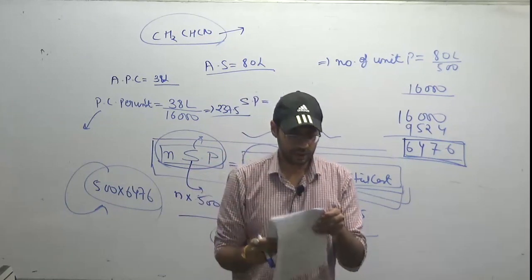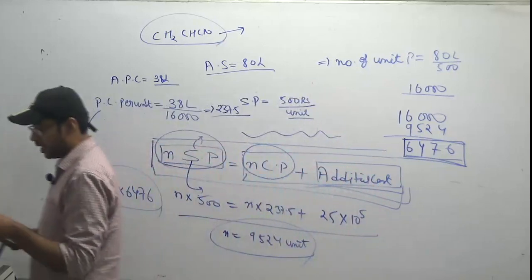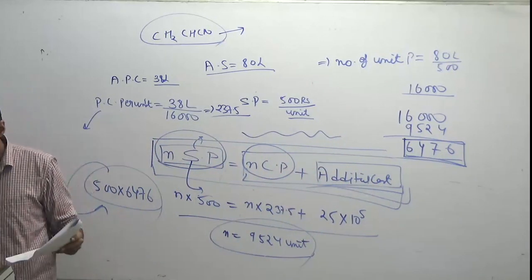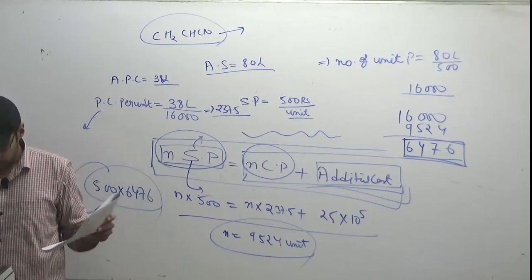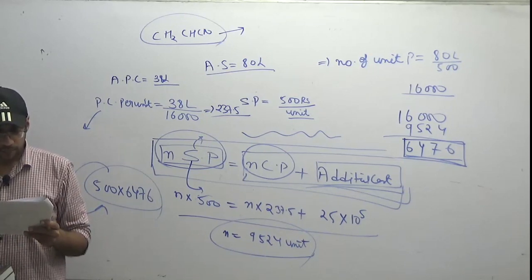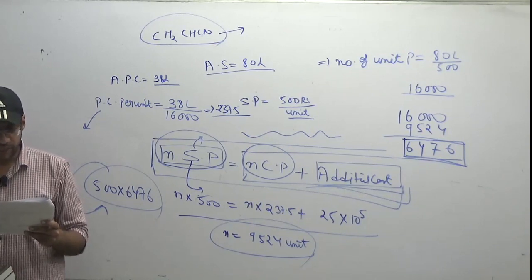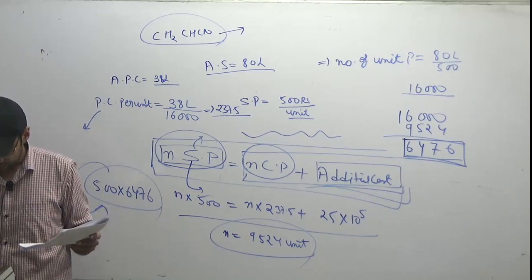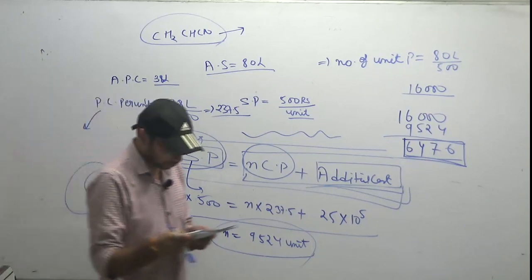Yes, now question number 23. The sensitivity and proportional band of a pneumatic controller with a scale range from 0 to 120 degrees Celsius, when the output changes from 20 to 100 kilonewton per meter square as the temperature rises from 95 to 110 degrees Celsius, are. They are asking about this thing, right?